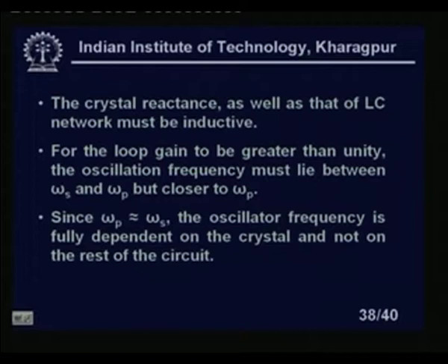Since omega p is almost equal to omega s, the oscillator frequency is fully dependent on the crystals and not on the rest of the circuit. This is the most important point of the piezoelectric crystals. You see here,